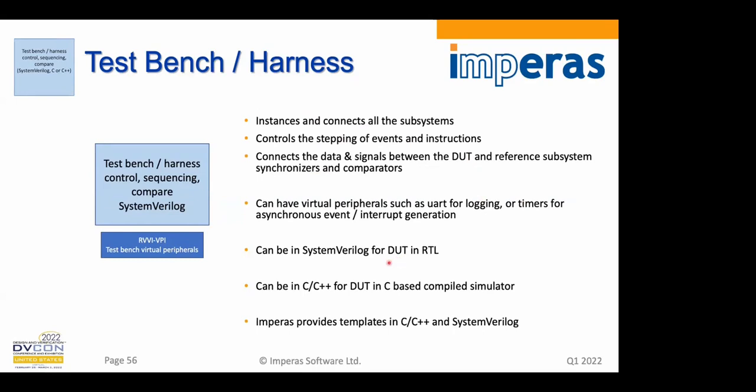And a test bench can be in SystemVerilog, or if you're using a C-based simulator, it can be in C or C++. And we actually provide templates with our environment for both C and C++ and for SystemVerilog usage for CPU DV.